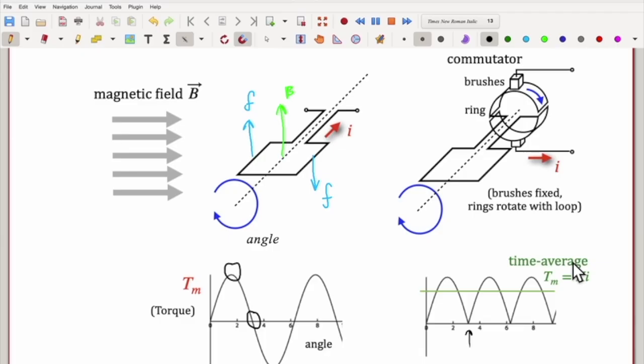So with this, we have now a system that can generate continuous rotation. I want to mention there's another category of motor that's becoming more popular these days because it has some benefits at the expense of complexity, and that's a brushless motor. The same principles apply for a brushless motor. The big difference is that there's no brushes, and instead a computer turns on and off the coils.